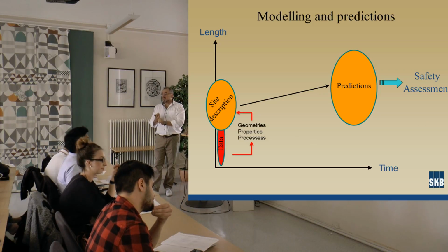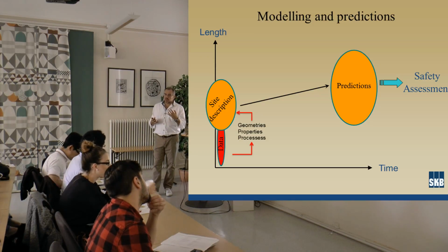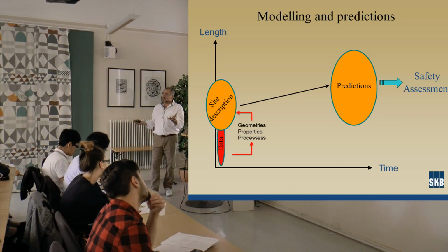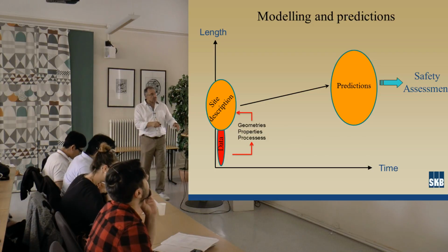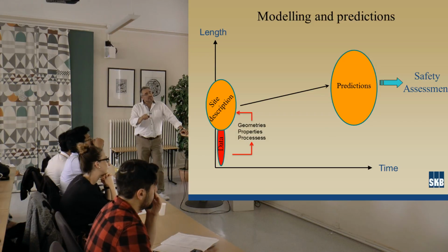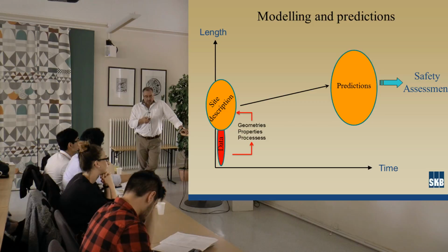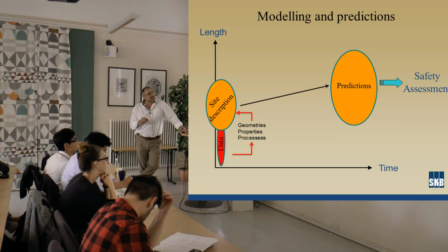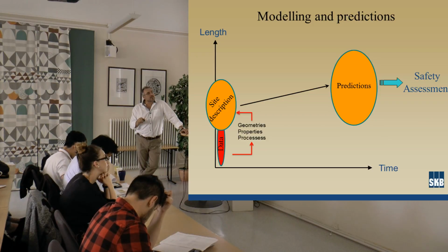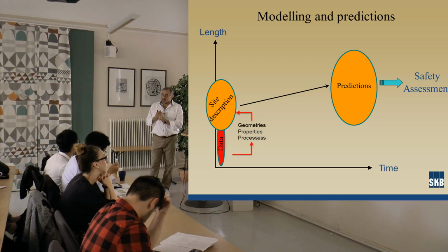The basic things are earthquakes, ice loads, and the penetration of oxygen-rich water down to repository depth, which is a critical issue in terms of containment. So this is what it is utilized for in safety assessment, going to predictions. This issue will be covered tomorrow by Patrik Widstrand, who is giving you a lecture on safety assessment. That is done at much longer time scales and somewhat greater length scales. This is then utilized to do the safety assessment, going back to the risk criterion, 10 to the minus 6 to the most exposed individual.